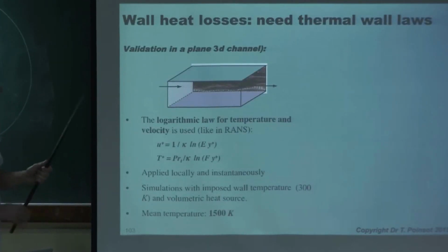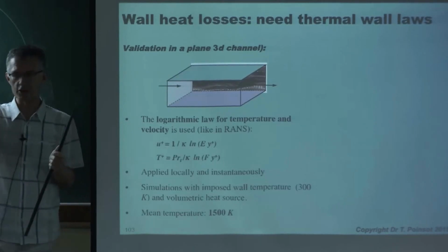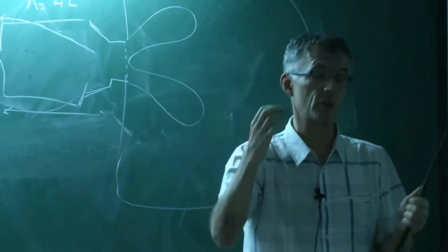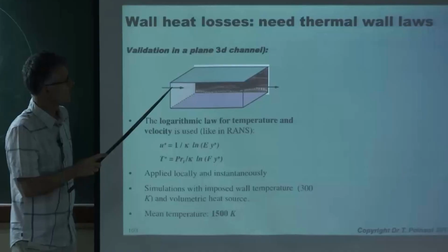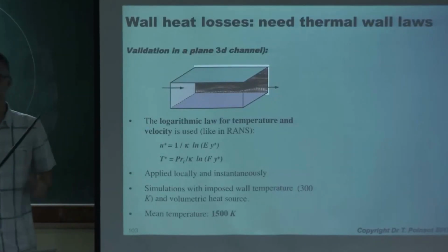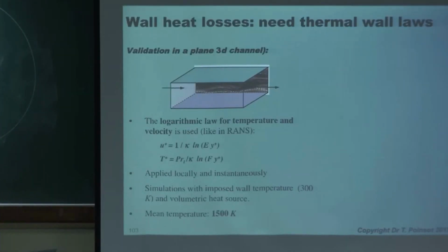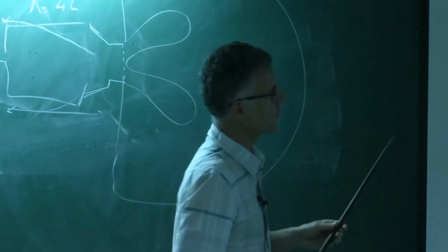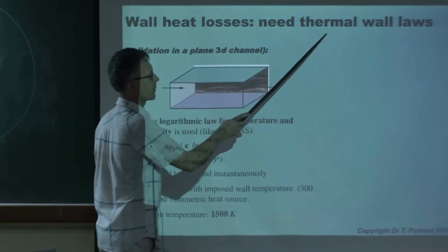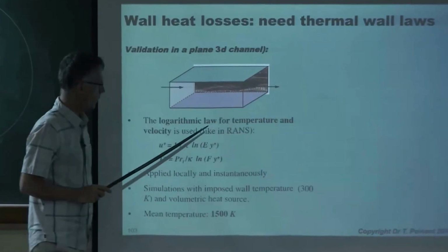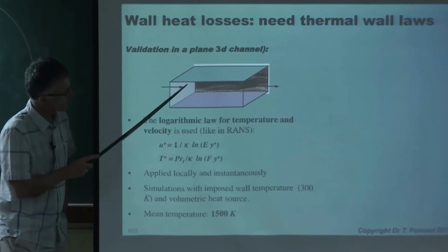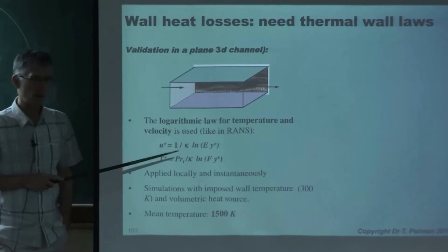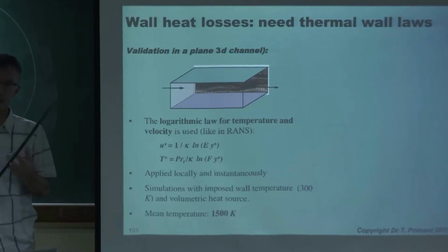The other thing you need to do, and that's something we have not really touched here, but I know that if you do LES, you're going to have to worry about that. You need to do something with the law of the wall. We don't usually have the resolution to go very close to the walls. So what we use is thermal and actually dynamic wall laws too. So the law of the wall is a way to avoid going too close to the wall.